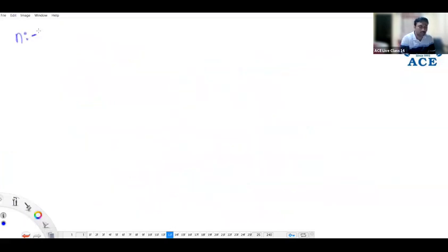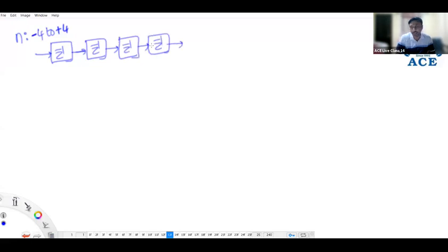Assume the data is available from -4 to +4; that is non-causal. If you cascade a minimum of 4 delays to the existing system, it causes a right shift of 4 samples, so the index -4 to 4 becomes 0 to 8. So a non-causal system can be converted to a causal system. One technique we are following is windowing. Another technique is shifting.